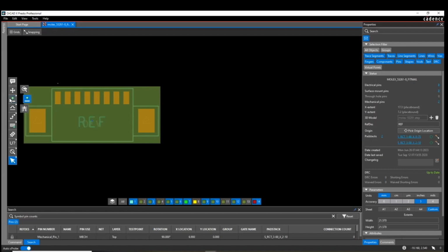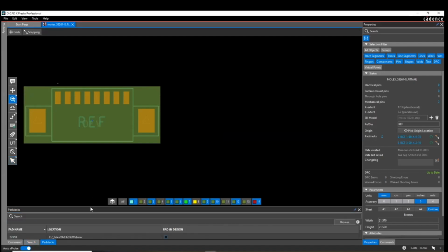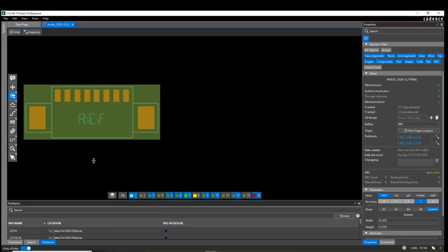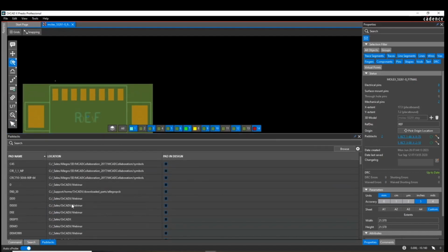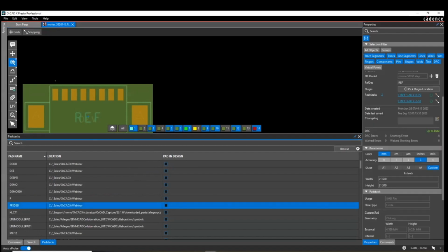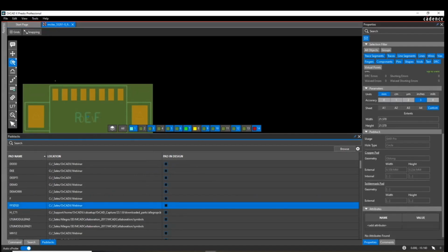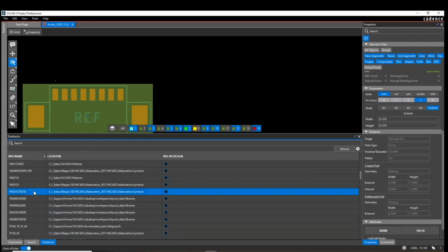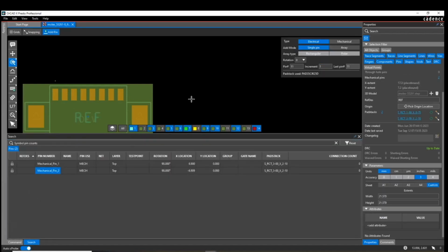Or if you know you already have that pin somewhere in your library, we give you a nice pad stack search capability where we give you a list of all the pads that are in your design. And then as you select those pads, you can see all the parameters of that pad from your library. For example, here it shows you that it's a circle, diameter, annular ring, has a solder mask pad that's different on every layer. That's why you're getting those triple dots in there, or if it's another through-hole pin, you can see all of its information. So this allows you to find the pin that you want, and if that's what you want, you double-click it, and then that pin is attached to your cursor, and you can add it in.